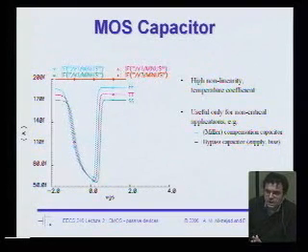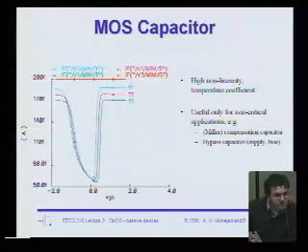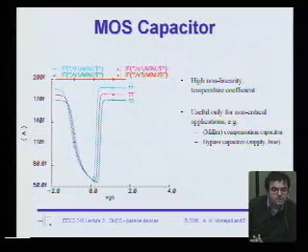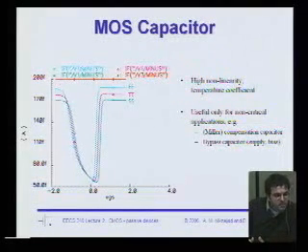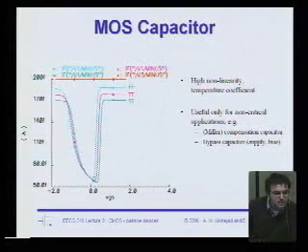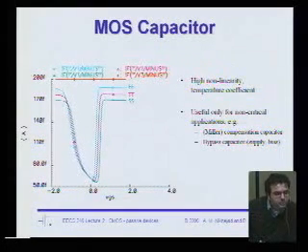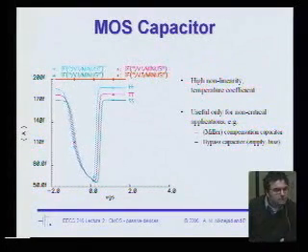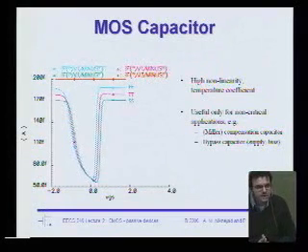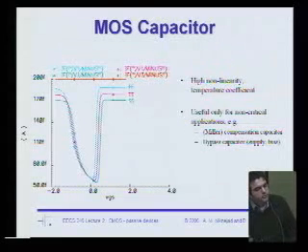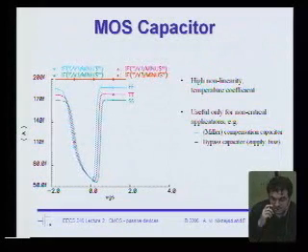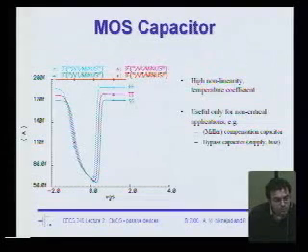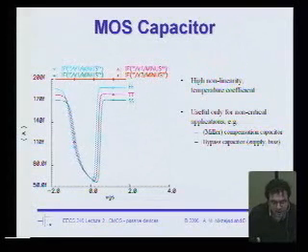You guys will probably witness that change because it's just way too pessimistic to try to make your circuit work at all these process corners. It's much better to do statistical design. In other words, if you have a transistor model that's physical, then I can physically vary the parameters of that model, let's say the channel length, channel width, the oxide thickness, the mobility, the temperature, whatever I know that's varying, and then I can do some Monte Carlo simulations. So in fact, I can run some Monte Carlo simulations and see what the yield of the circuit is going to be. If the yield is high enough, say it's 98%, great, ship it. And it may not satisfy the process corners. So that's something that is historical, and if you go out and work today, you will be working with process corners. It's very common, but something that I think is going to change in the next few years.